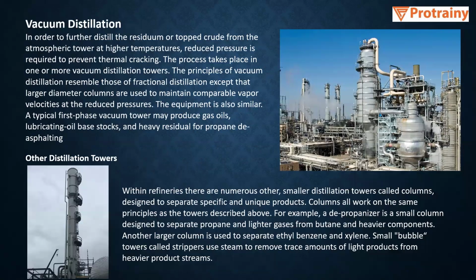So vacuum distillation. Okay, in vacuum distillation, we do the distillation under vacuum. So here it will be at high temperature, and the pressure will be reduced to prevent thermal cracking. So whatever components are there will also be further extracted using the vacuum distillation.